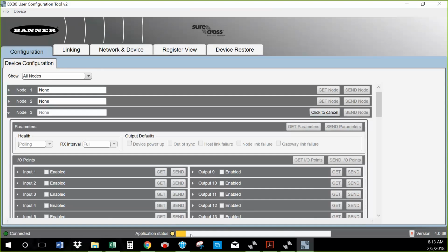Now, this is a really important step when you're using a battery or a flex-powered node, because the report rate and the polling rate are very important to you. You want to make sure to set those at a time long enough so that you're not just killing your battery. I know early on when we first brought this out, we had a few issues with the battery polling too fast, and we were just killing the battery.